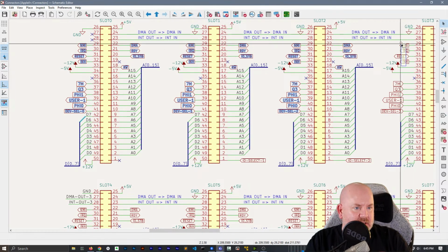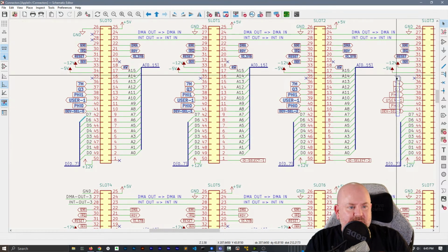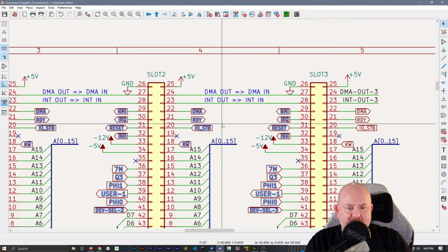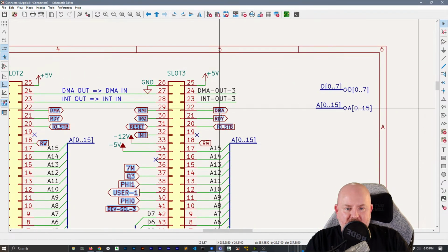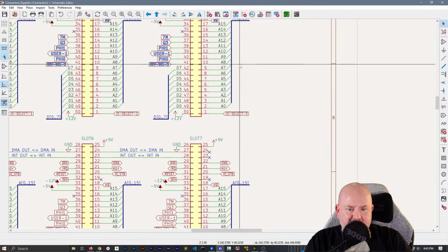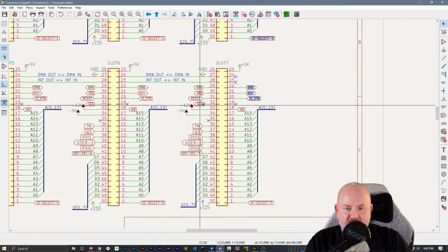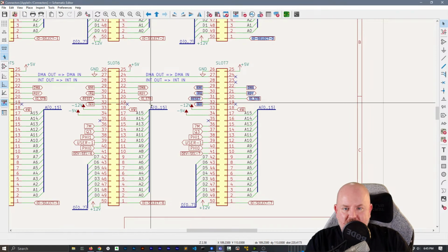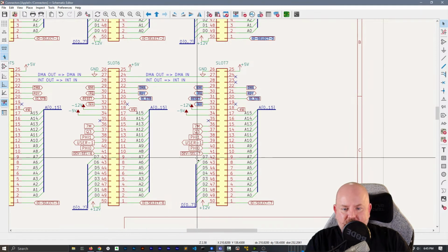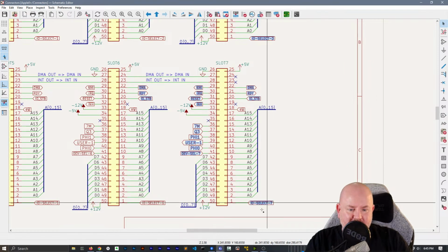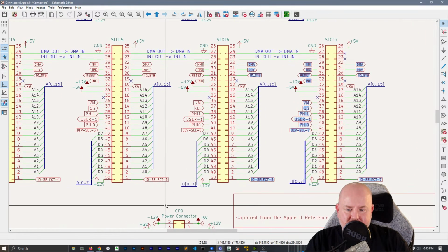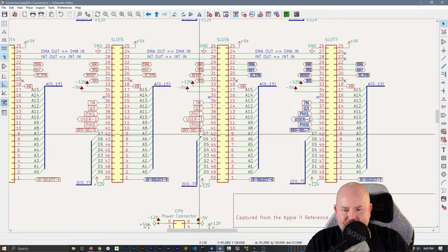Now that I've had a couple of designs fail because of that little trick, I have decided it is worth the time and effort to set up pins correctly and run ERC to see what it finds.